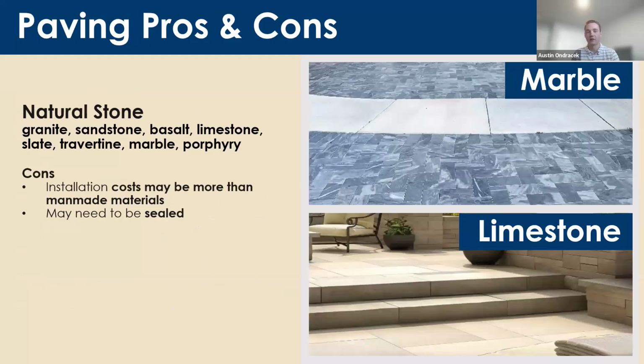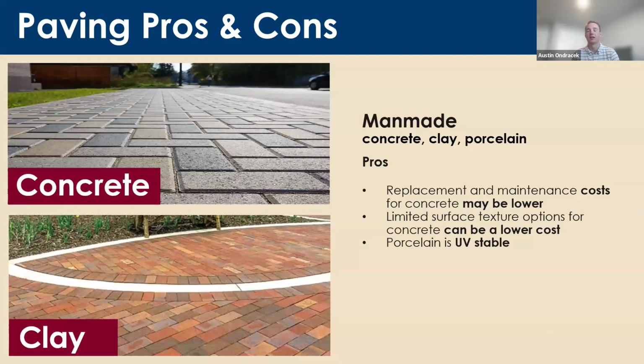Some of the cons of a natural stone in a paving application can still be that installation cost is more than that of man-made materials. And then something to always consider with a natural stone is many of those products still need to have sealants applied, similar to that of paving applications that are man-made material. So it is durable. It does do very, very well in paving applications, but some of them do need to make sure they are properly taken care of to make sure that life cycle cost and that lifespan is extended for as long as possible, depending on the application it's installed in.